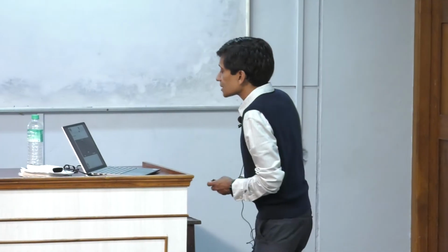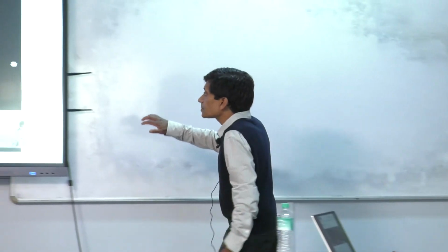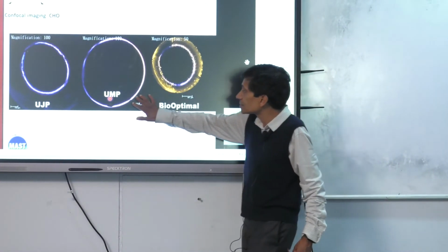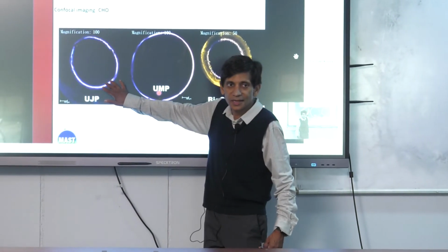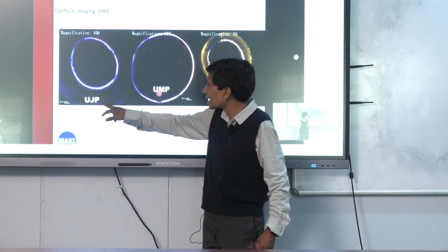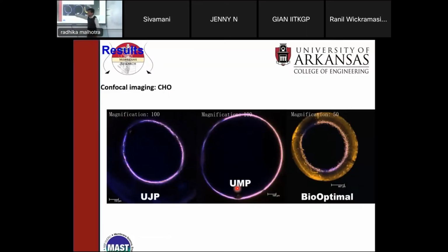And if you look at here what happens, so this is the biooptimal, okay? This is the one that has this reverse asymmetric structure. But these are traditional microfiltration membranes where the barrier layer faces the feed. So there's nothing in the membrane. It's all on the surface. But here you can see this really is acting as a depth filter. You're getting significant adsorption inside the membrane. And that's what allows you to actually have the much higher fluxes, okay? And the much higher capacity. So this is a very interesting membrane.